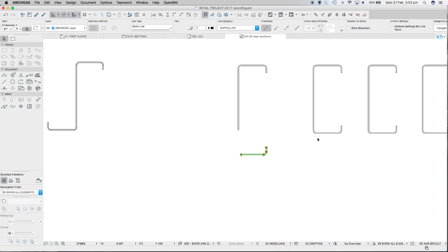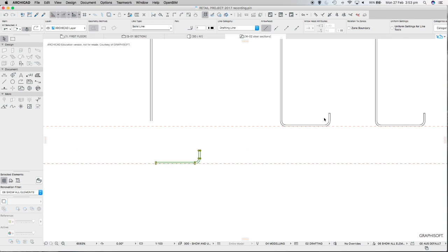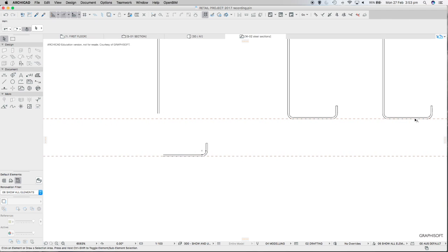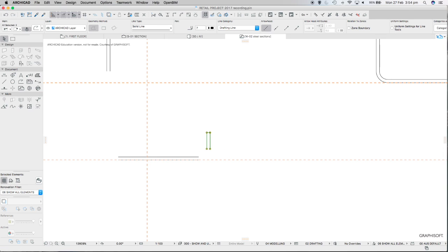And then this is where I'm going to make use of these other entities here. For starters, I'm going to set up the thickness of this with another guideline. So I'm pulling another guideline over to this edge, and then I'm going to bring that guideline across maybe, let's say, 25 millimeters. Now I'm going to use my trim tool to then trim off that piece and that piece, so that I can then pick up these two pieces as one and drag them across